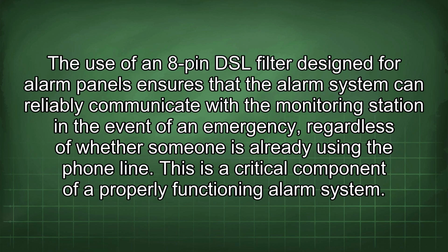The use of an 8-pin DSL filter designed for alarm panels ensures that the alarm system can reliably communicate with the monitoring station in the event of an emergency, regardless of whether someone is already using the phone line. This is a critical component of a properly functioning alarm system.